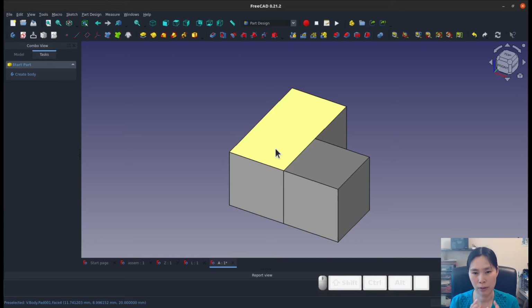So sometimes it messes up. Anyway, I'm going to show you about the external geometry later, but now the other option is that we can extrude this instead of up from the top surface. We can extrude it down so that the other part up creates exactly the shape we want. I'm going to show you right now so it's easier for you to see.